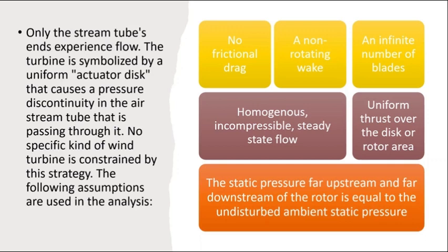The following assumptions are used in the analysis. First, no frictional drag. Second, no rotating wake. Third, an infinite number of blades. Fourth, homogeneous, incompressible, steady state flow. Fifth, uniform thrust over the disc or rotor area. And the last, the static pressure far upstream and far downstream of the rotor is equal to the undisturbed ambient static pressure.